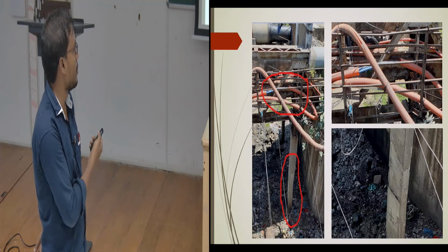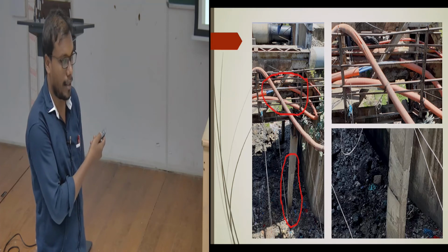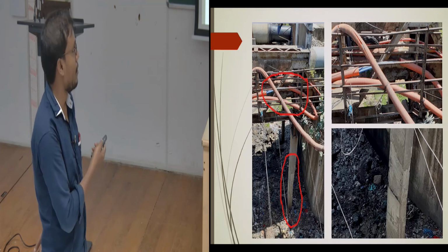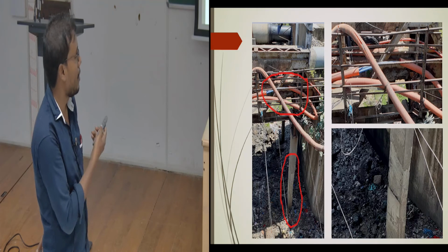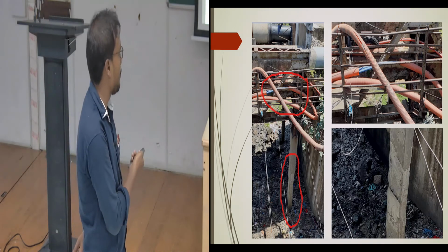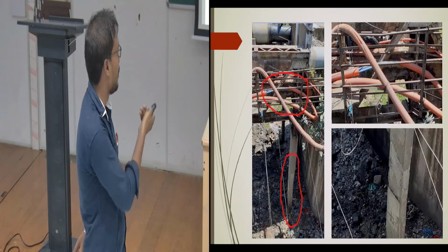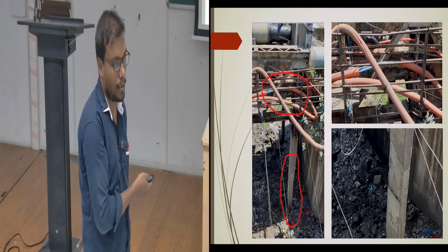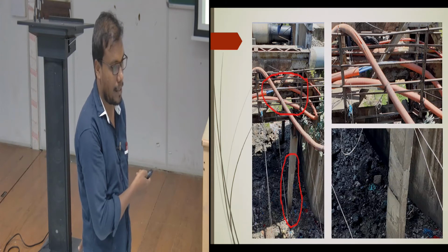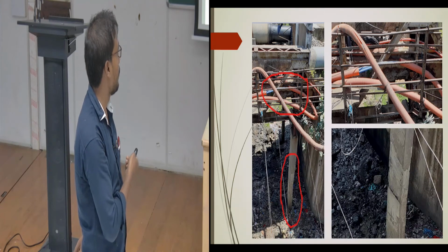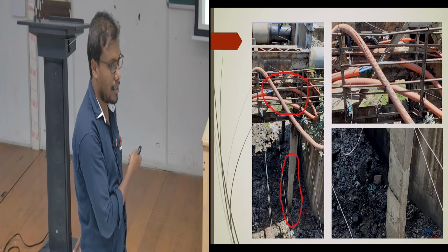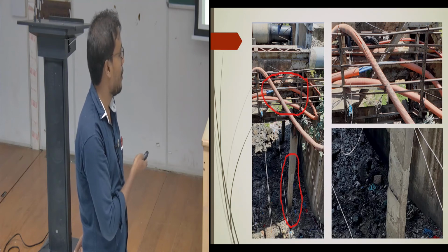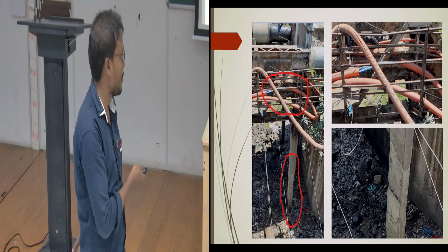It is carrying a heavy mass of water, according to the volume. It can even cause breaking of the pipe at that joint, if it is not being supported here. Here are the two causes. One is deterioration of this concrete support, and the other is buckling of this column. So it totally fails.